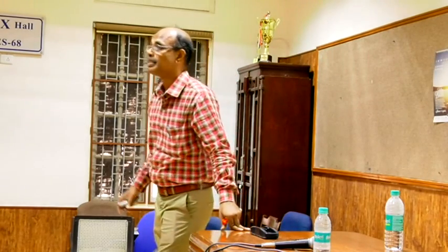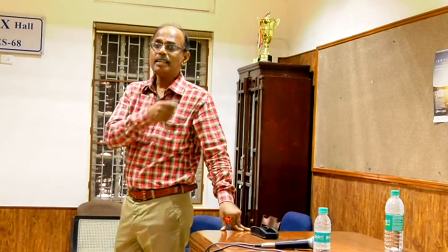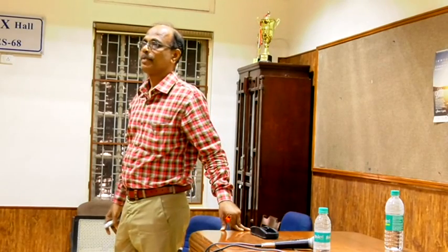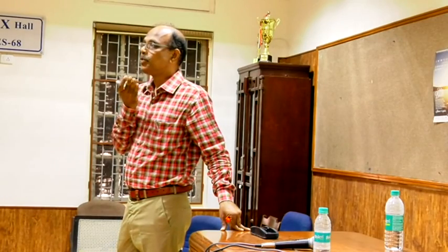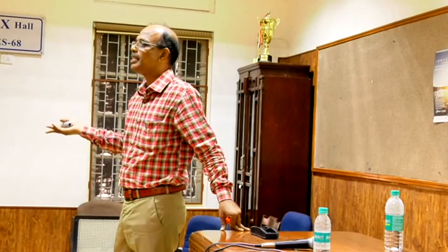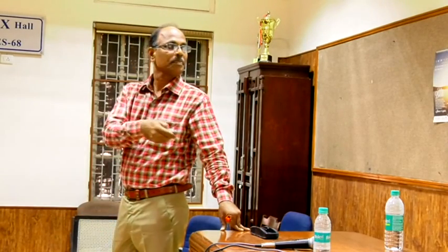The values of Q's are specified. There are 8 equations and 8 unknown parameters. There is another set. So totally earlier 12 plus 8, 20 equations we have now. We have 20 nonlinear equations, we have to solve them, that's all. The variables are V's and deltas. If you can apply some technique to find V's and deltas, then that is the load flow solution, the load flow problem. Right.